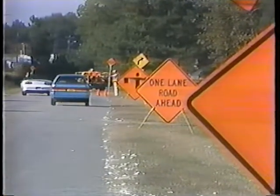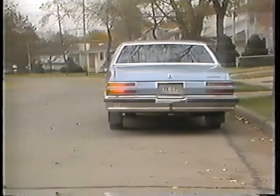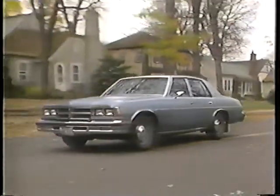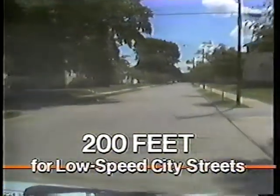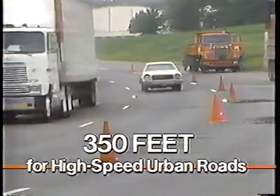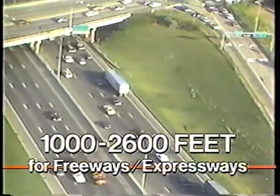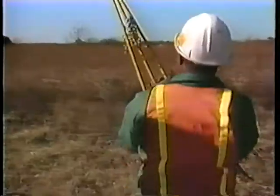In keeping with the Manual on Uniform Traffic Control Devices, a rule of thumb for the spacing between signs in a series is 200 feet for low-speed city streets, 350 feet for high-speed urban roads, 500 feet for rural roads, and 1,000 to 2,600 feet for freeways and expressways.